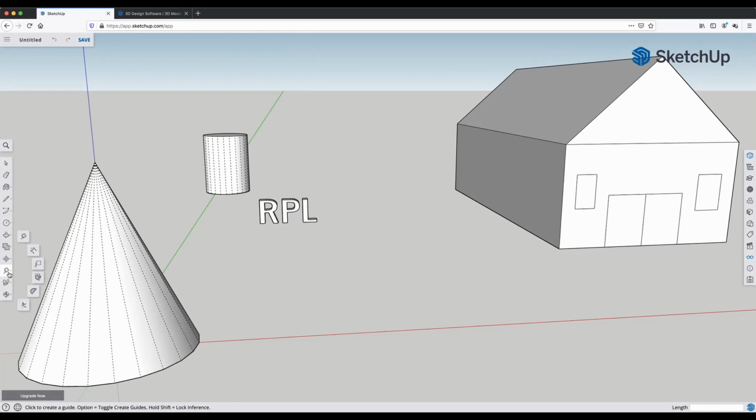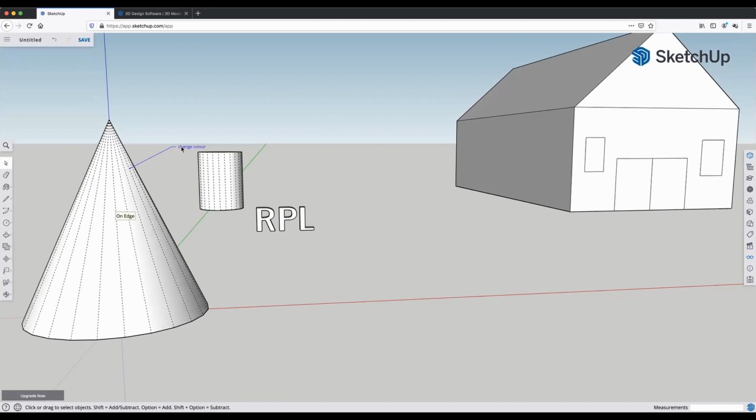And then we have this menu right here, where we have our tape measure. We have our dimensions, so we can measure out our models on the canvas here. And we have a little text tool. I'll show you how this works. If we click once, it's giving us the dimensions, but we can change that and leave little notes for people, basically. So we can say, change color. There we go. So that's how that works. And if we don't need to have this there, we can just click delete and that'll go away for us.